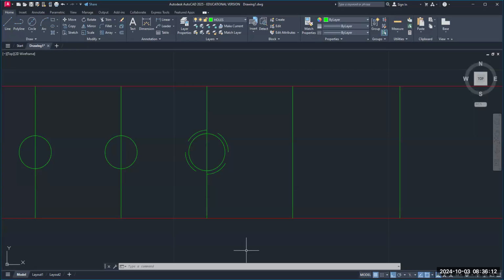So you're, let me see your mouse. So when you draw your first circle. Oh, I see. Your snap, so type in O snap, OSNAP. Enter. And you want to pick midpoint. Yes. Okay. Another circle.